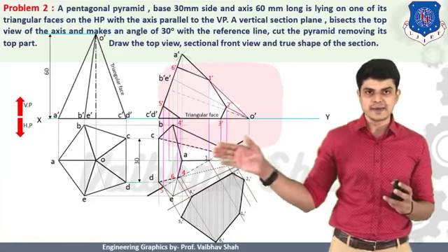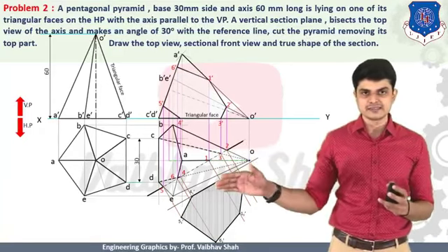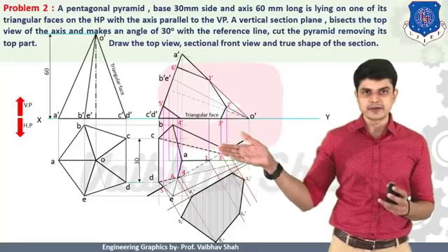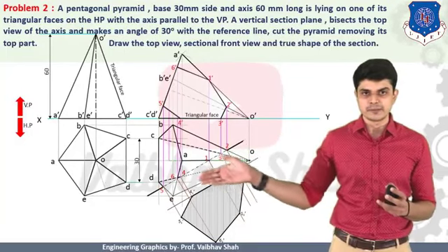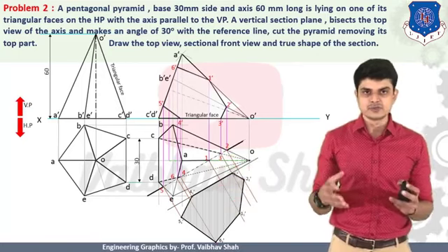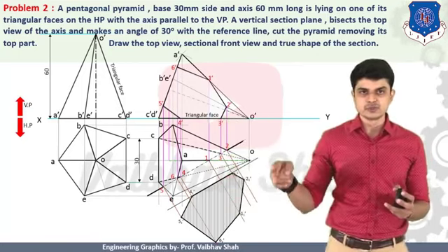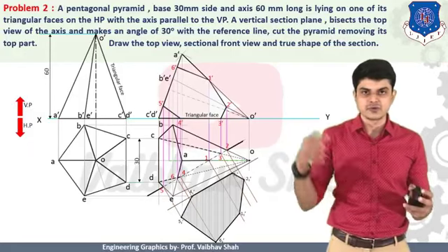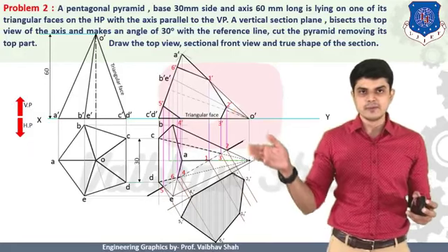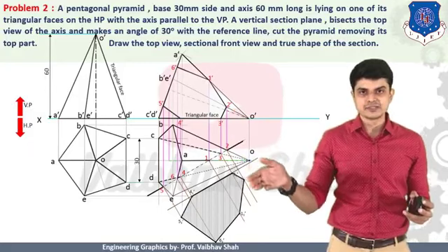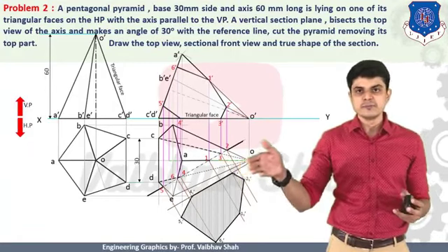You should draw a line parallel to this cutting plane line like this, and now you should draw the perpendicular lines from each and every point on your cutting plane line. Then after, you should assume that this parallel line is nothing but your xy line in our case, and you should take the dimension of each and every point onto xy line, and you will be putting that same dimension with respect to this new parallel line.